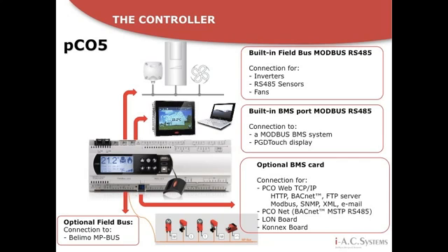This port hosts plug-in cards with BACnet over IP and BACnet over MSTP, SNMP protocol, XML and email facilities on the web server of the Ethernet interface card, Modbus over IP and Modbus over RS485, LON and Konnex protocol.